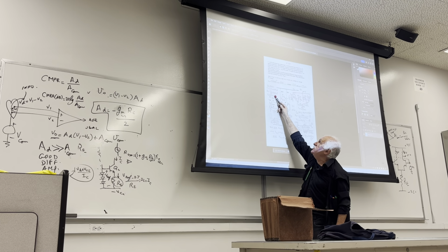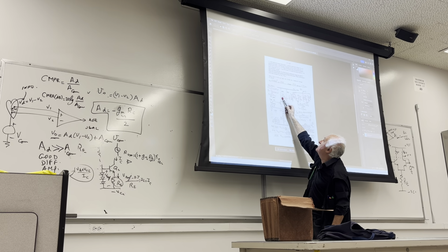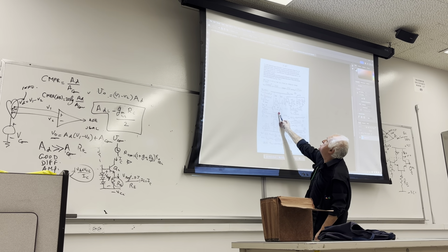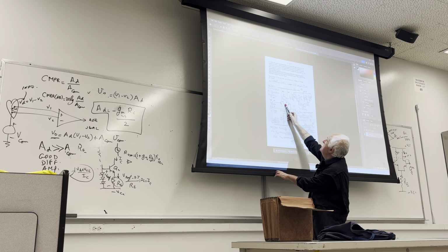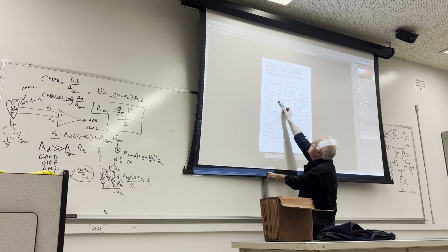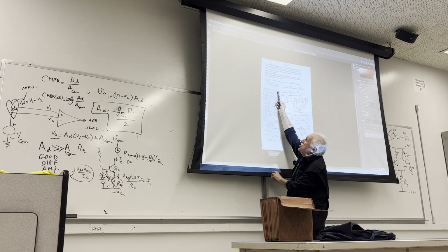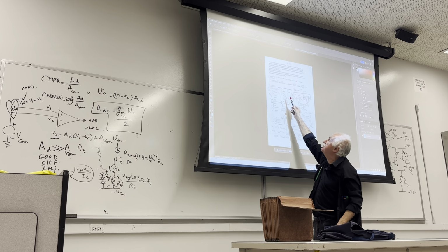You calculated GM over here, multiply by the RC, whatever the value is. It tells you what the values are. RC is 1.28K. Stick it in that formula. So our differential voltage gain is 13.5. It's not much, just 13.5.